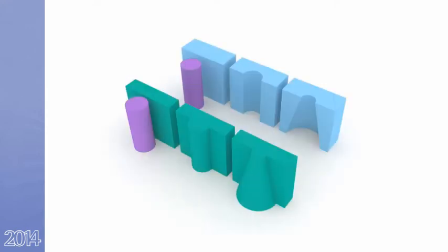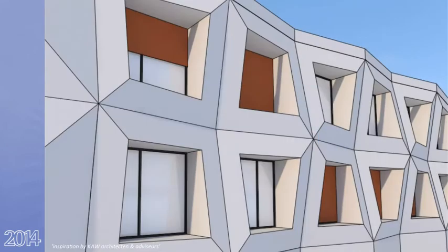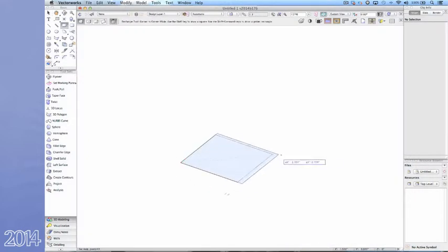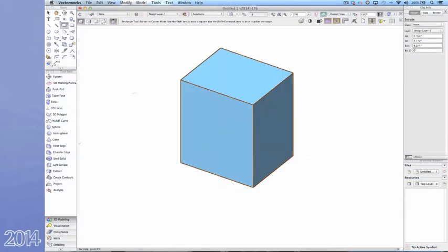In a continuing effort to help you embrace the concept of designing in 3D, we now have a couple of new additions to the direct modeling family of tools. The first, Taper Face. Let's start with a simple cube, and from the 3D modeling tool set, we'll select Taper Face. First, we'll select a planar face as the base reference. Then, select the face you want to modify.